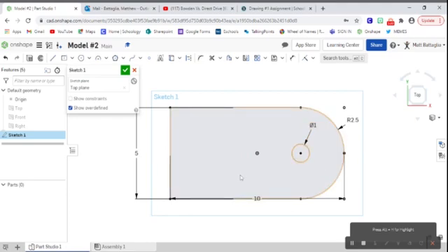If we look at the drawing, we have another circle a bit of a way down. In fact, it's 2.5 inches from the center point of this circle. If I click here and go directly to the left 2.5 inches, you'll see, believe it or not, I'm actually directly at my origin point. But it is still good to use these references. So let's say I hide my origin, and then you can see my endpoint there. At that endpoint, I'll place another circle. This circle is going to match up with that 1/2 inch radius or 1 inch diameter.